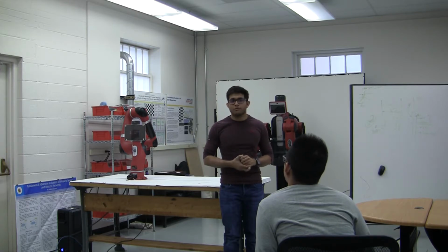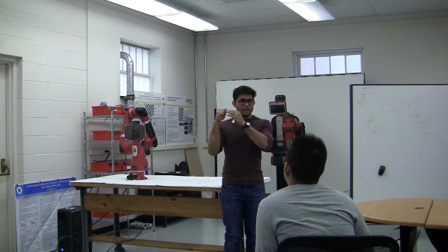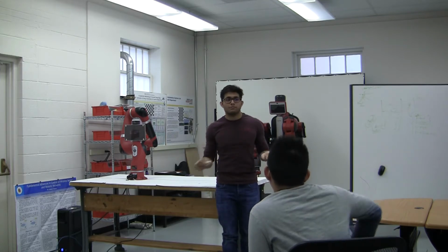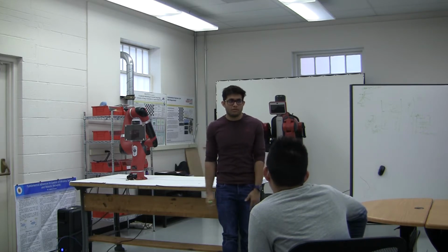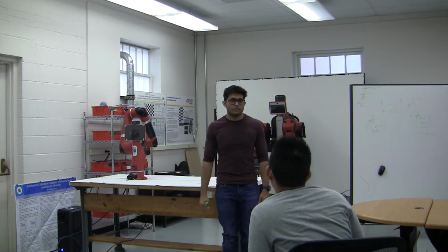But always before running the robot, we can run the simulation. If your URDF model is correct, it will run perfectly in simulation. It will show you in RViz that the camera is connected to the wrist. That's why we are asking you to show us a demo in simulation, because if you do that, it means we are perfectly fine and you can run the robot. That's why ROS is good enough. Topics are the same when you run the simulation or the robot.